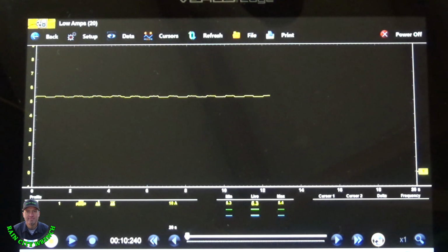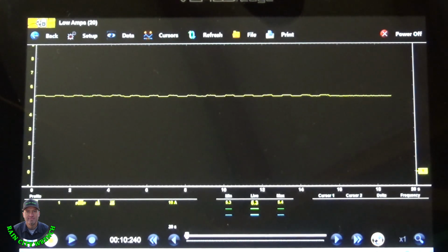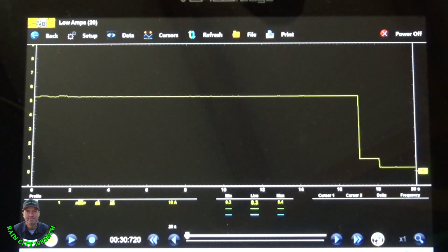So it looks like all my interior lamps are on. Let me shut the door, and you're gonna watch this body control module start turning lamps off when they time out. It's on a delay. Okay, I heard it click off.